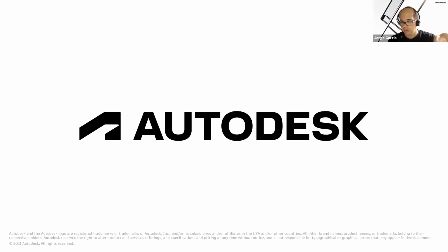So if something changes with the enclosure, now you had a switch and now you need to make room on the board, you go back to the enclosure model, you change the sketch. As soon as you save it, the 3D PCB sees that something changed, you update it, 2D PCB sees it, you update it. So if you have an enclosure that's standardized and that's what's going to be driving the design, then you do a derived PCB from there.